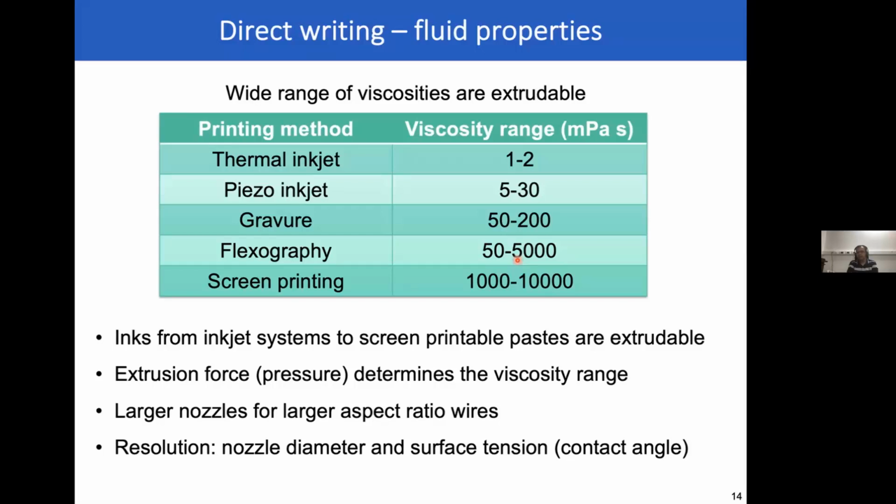It may only serve as a top electrode, because I don't know any other way of controlling the roughness, because these are just randomly dispersed. You're just going to have some situations where 2 nanowires are on top or 3 are on top. So you would invariably end up with a rough surface, is my feeling. At least not the kind of roughness you would expect in, say, vapor deposition. Okay, thank you, sir.